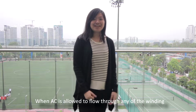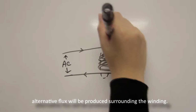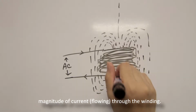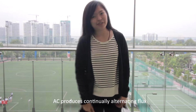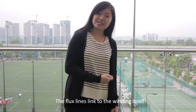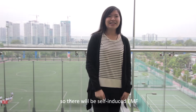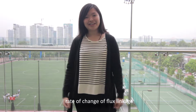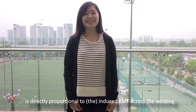When alternating current is allowed to flow through the winding, alternating flux will be produced surrounding the winding. Hence, we can say that the magnitude of the flux is proportional to the magnitude of the current through the winding. Alternating current produces continually alternating flux surrounding the winding. The flux lines link to the winding itself and are varying, so there will be a self-induced EMF. This is according to Faraday's law, where the rate of change of flux linkage with respect to time is directly proportional to the induced EMF across the winding.